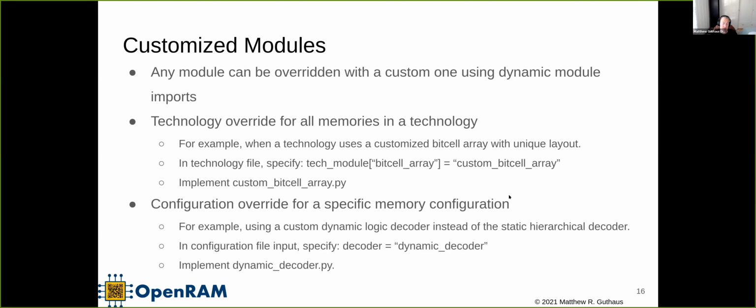Well, because this has to be portable to many technologies, a lot of the things are connected by just abutment placement. For example, the array is connected, the decoder is connected. Each of the address part, the data part, and the array and the control logic are all connected kind of on their own. But then at the chip level, or the memory level, I guess, we need to connect the power.